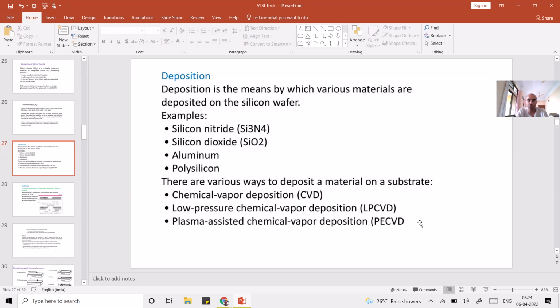In sputtering, we just remove the atoms by continuously bombarding the material. Whatever material we want to deposit, we keep on bombarding it with a very high energy material. By this continuous bombardment, that material loses some atoms. Those atoms are allowed to settle down on the substrate uniformly, and while sputtering, the substrate is continuously rotated as well. When you spin it, the distribution of the atoms is uniform.